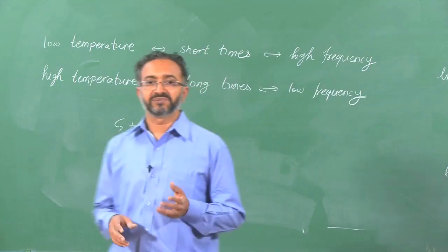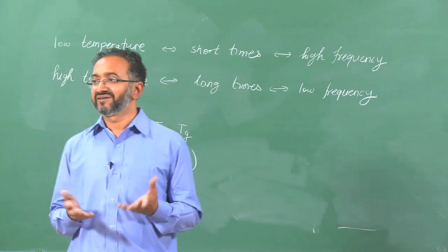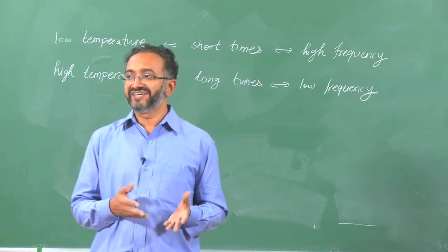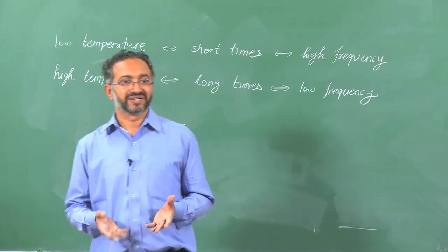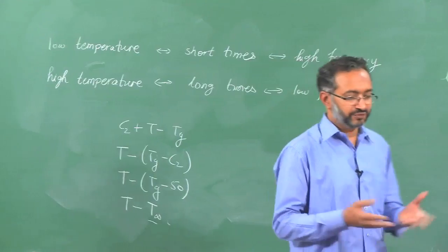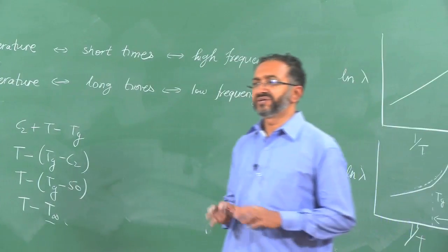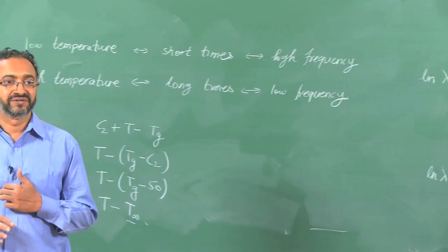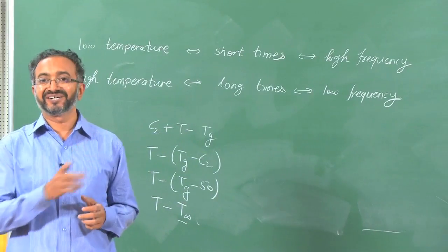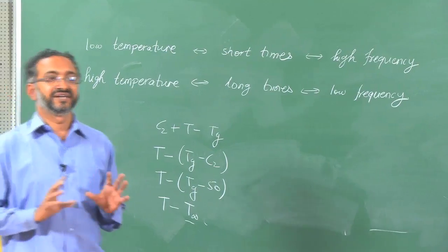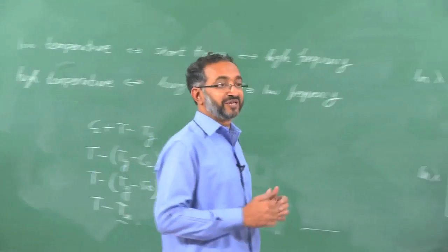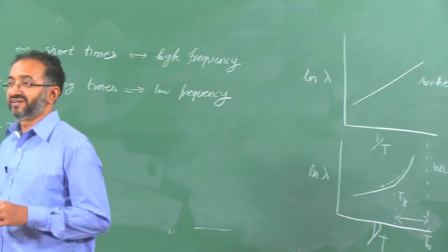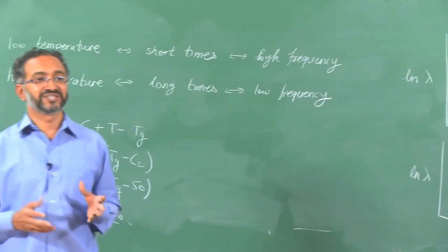So, the glass transition temperature is around 75, 79, around that. Therefore, below Tg minus 50 is around room temperature, 25, 30. So, you can expect the material to not really have much relaxation, but if you put 60 degree, 70 degree water in it, then you are allowing many more relaxation processes to happen in the material, at relaxation times of, say, 1 year, 2 years, certainly things will happen.